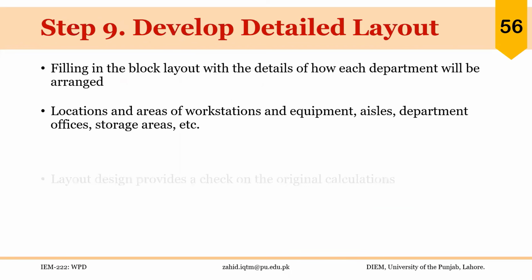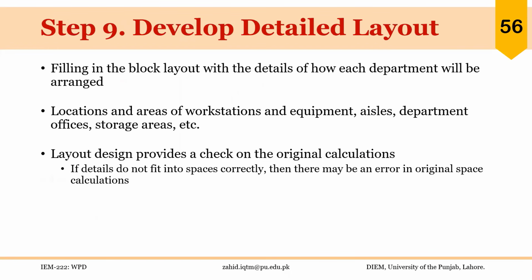The final step is to develop the detailed layout. This means filling in the block layout with the details of how each department will be arranged: locations and areas of workstations within each department, aisles, department offices, storage areas, everything is shown. So layout design provides a check on the original calculations. If details do not fit into the space correctly, then there may be an error in the original space calculations.